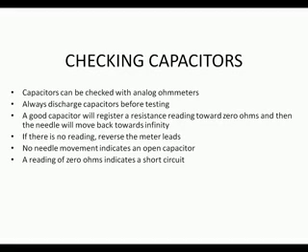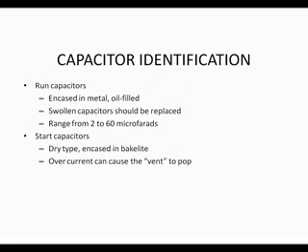Motor starting problems are relatively easy to troubleshoot. Check for full power to the motor. If I don't have full power, the motor's not going to start properly. If the motor hums but doesn't start, you might have a starting problem, like one of the start components is not closing. The motor may run for a short time and then shut down, or the motor might not attempt to start at all. If the motor turns freely, examine the electrical circuits. If the motor hums but does not start, the starting components should be checked.